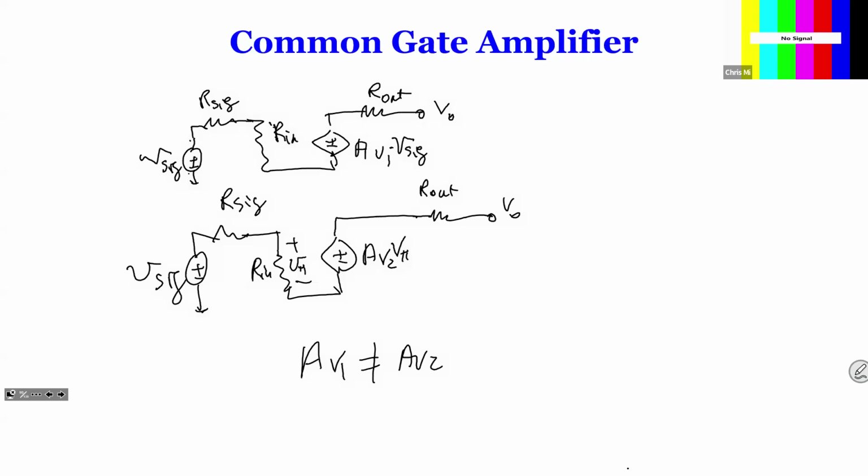So, okay, that's what we have. Maybe now if you connect a load resistance, for example, if voltage is 10 volts, your resistance is 5K, your load is 5K, now your output is actually half of the voltage gain here. Now, if it's a current source over here, remember what we do is we have these two in parallel, which basically gives you the same thing, because when they're in parallel, your resistance is reduced by half, and your current is constant. So constant current times half the resistance also gives you half of the voltage. So exactly the same output.